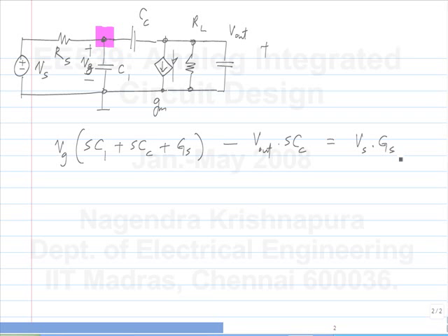Is it okay? This is okay? What about the second equation? The equation here. What's the coefficient of Vg in this case? So in each case, what I have drawn here on the left hand side are the currents flowing out of that node, and the right hand side is the current source that's injected into the node. Okay, effectively, that's what it is.